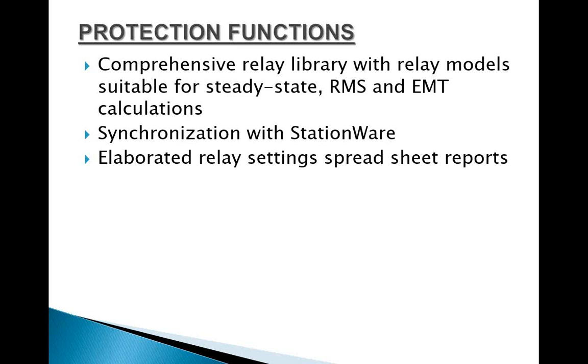So synchronization with Stationware is possible. Highly detailed relay setting spreadsheet reports are there. Graphical visualization and editing of fuses, relays, and CT/VT are possible. We have time overcurrent protection, distance protection, and also directional relays. So these are some protection functions we have.